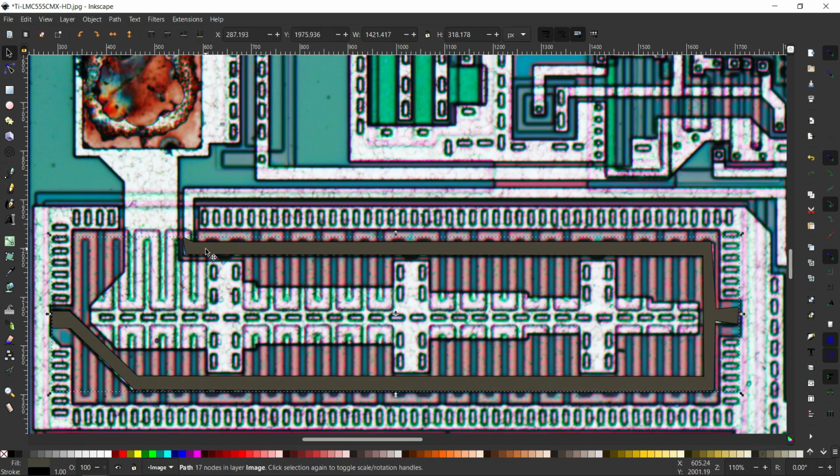See, this net is the drain connection. They have taken the drain connection here, whereas the source is by default connected to the guard ring using a different structure. Internally, see how they have taken the source connection here. This is your drain connection, and in between some metal is flowing through, right? So this is your gate connection.